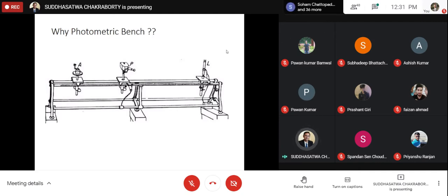There is a general rule of thumb, a general practice that we follow, which is basically the geometric center of the light emitting portion of the source. Because there is a big source where the light part is there, and a small part is there where the luminaire, other assembly like control gear, ballast are placed, we will see later on. But this point is a very specific point where, for these sources, only the light emitting portion we need to consider, find out the geometric center of this one, and that will indicate the photometric center of the source. Okay, so that is the photometric center.